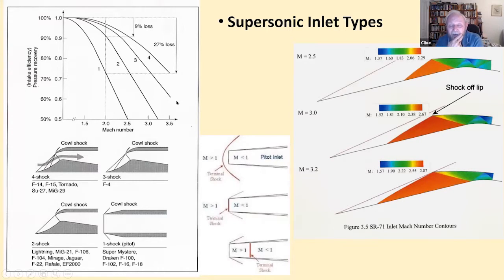The other end, or perhaps extreme, of these supersonic inlets is the internal compression inlet, in which nearly all the compression from supersonic to subsonic flow takes place inside the confines of the intake. Most intakes, in fact practical ones, are known as mixed compression intakes, which is a bit of each.